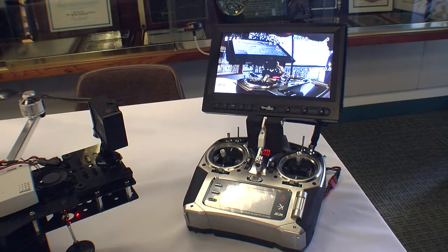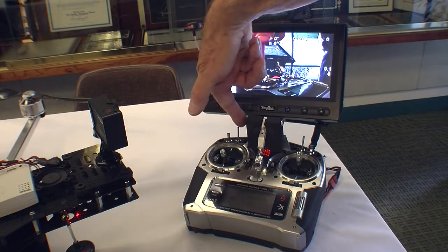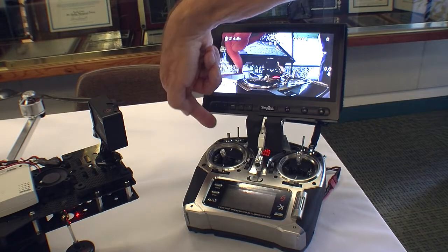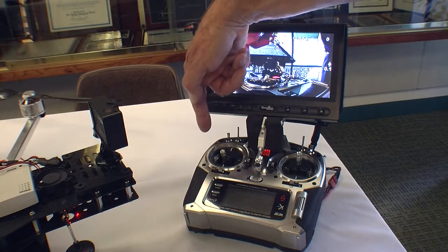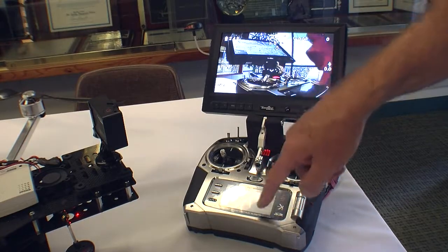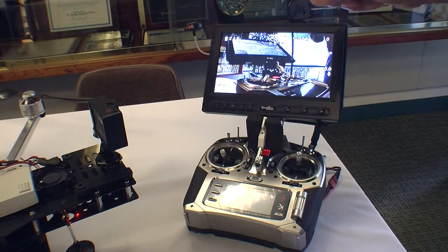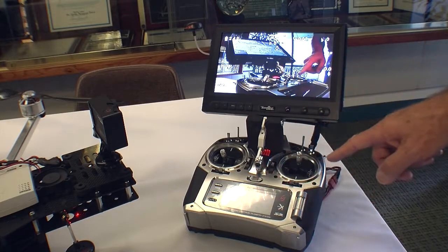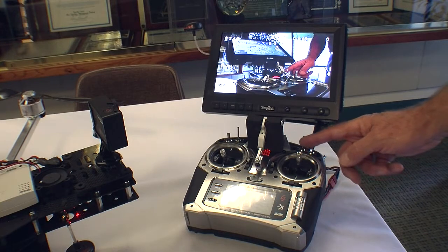This is the transmitter unit that's used for controlling the quadcopter. You've got the various flight controls. There's a number of switches that are used to switch modes of operation for GPS control or just a simple attitude adjustment. The throttle and positioning controls are down in here. There's also a flight screen right here that gives you real-time information for both temperature, for flight parameters, for how long you've been running, how long you've been airborne. The switches that are used to control samplers are all over on the right side.